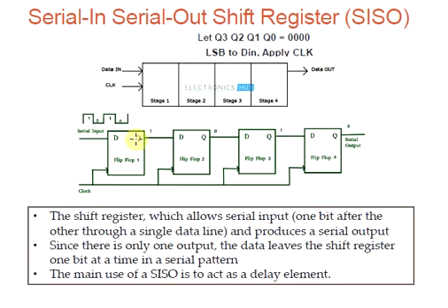And here you can see the corresponding logic circuit for a serial in, serial out register. The circuit consists of 4 D flip-flops which are connected in serial manner, and all flip-flops are synchronized with each other since the same clock pulse signal is applied to each flip-flop.